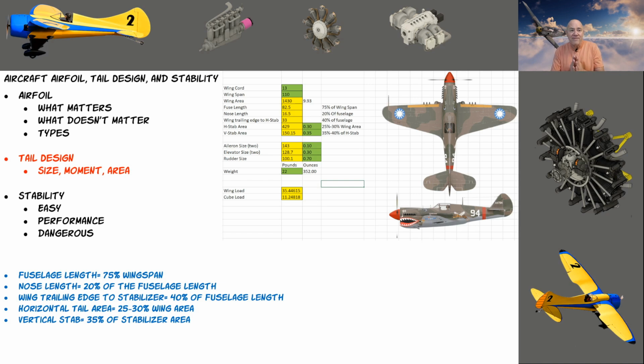If you're going to have an airplane that has a short coupled tail, you want big elevators and a big stabilizer. You want more control. But you don't want 35 degrees of elevator throw on a high-speed servo without any exponential. And I know some of you have said, oh, I've flown 30 years without exponential. Congratulations, that's awesome. 90% of my friends fly with exponential on any type of high-performance plane or experimental plane or a scratch built. Anything that you make yourself, once you get it tweaked out perfectly, I would say almost 100% of my friends use exponential.